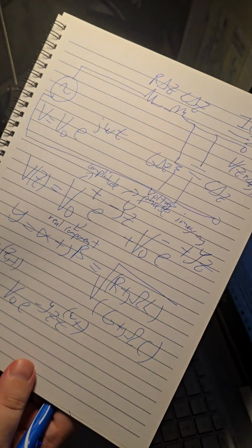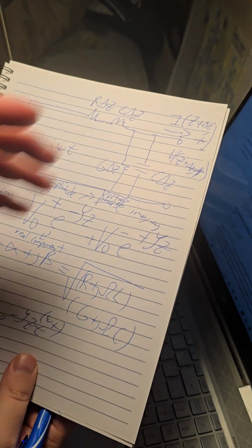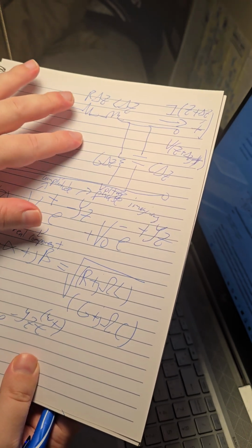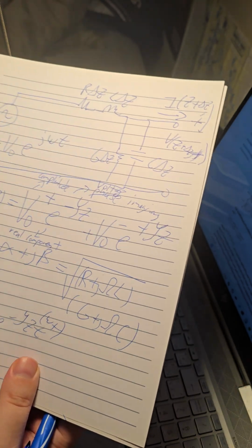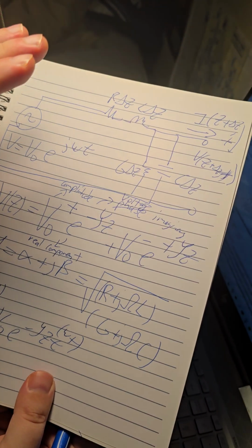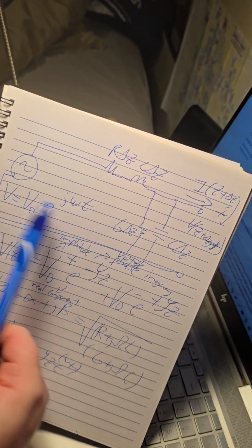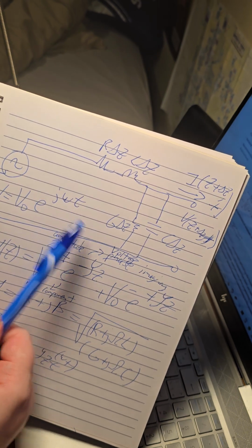And basically what we want to do is monitor how much reflection we're getting, because if we get too much reflection, it could explode, or it could cause dangerous high spikes at certain loads. Wherever our loads are, depending on what the reflection is there, determines how big the wave is. So we want to design, and the only thing we can really do is change the length of the line. We can't change the material it's made out of. So next to all our loads, we change the length of the line.